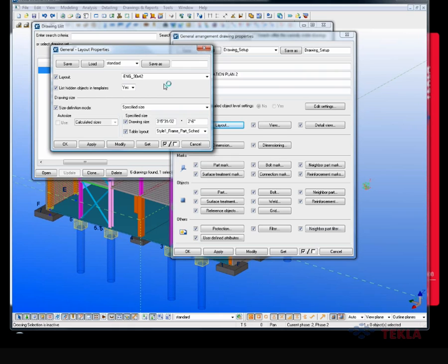So this is where you can see that information. So here's my layout. My layout's available again. So when I pick this 24 by 36, I can see those same layouts available that I set up previously within my template editor. So the information that you're really going to load in here is going to be based on what you set up already.